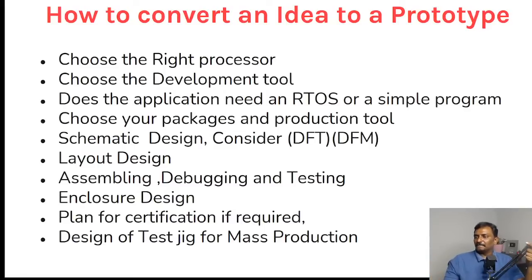Why is hex code required? Why not binary code? Pankaj Sri, mostly it is in hex format. There are different formats: Xilinx comes up with the executable linker file format, ELF, and only the ELF format will be downloaded inside the FPGA. Whereas 8051 downloads hex format, and Code Composer Studio from Texas Instruments downloads out format. Some will be hex format, some binary format. It depends upon the manufacturers, but mostly if you open the file which is going to be downloaded, it will be in hex format.